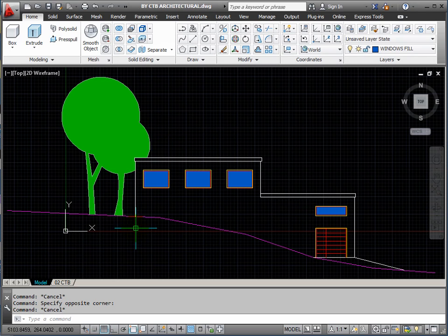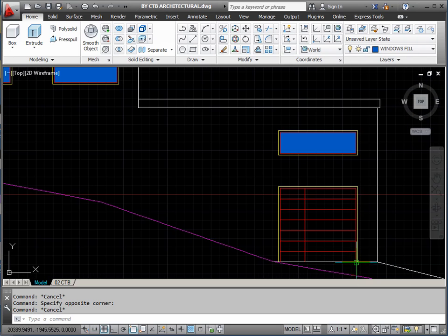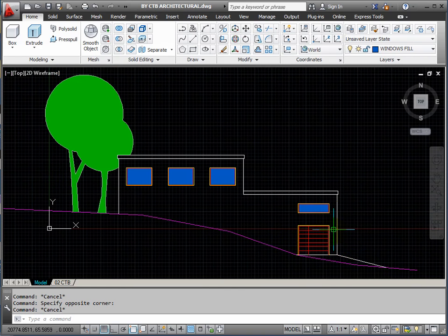So when I just look at the drawing, if you stand back and just look at your drawing, you probably can tell I'm standing back because I'm getting further away from the microphone. When I look at the screen with the black background, I can tell what's important and what isn't. You know, the detail on the door isn't really as important as the shape of the opening of the door. So we've got a yellow line highlighting the opening, and then the shape of the building, which is even more important, is using the white layer color.